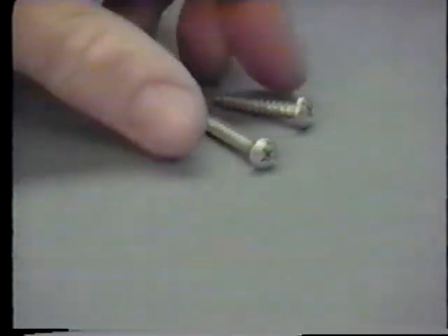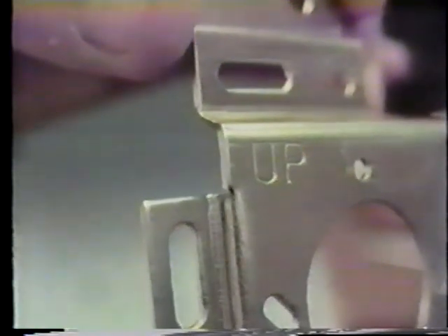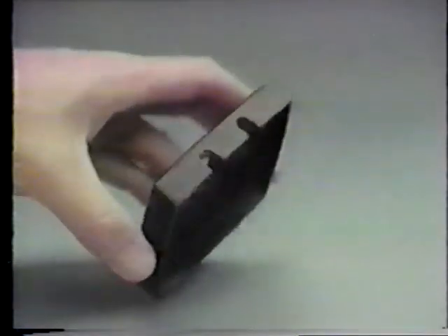Using the screws provided, mount the bracket to the wall vertically and centered over the old pipe head. Install the bracket so the stamped word "up" is positioned in the upper left-hand corner. On installations where air lines are surface mounted, the bracket must be mounted perpendicular to the air lines, and the notches on the inside of the wall plate must be cut out.